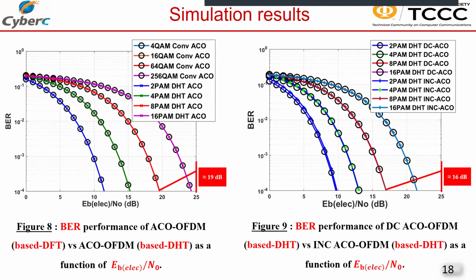It can be observed that both techniques achieve similar BER performances with an approximately 3 dB gain in SNR compared to conventional ACO-OFDM, as shown by figure 8. This improvement is due to the effective demodulation provided by both diversity combined and improved noise cancellation at the receiver. Both demodulators reduce the system noise impact by approximately half.